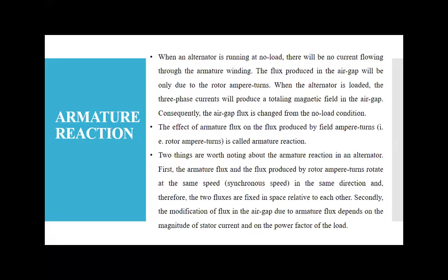Okay, you have a generator. It generates 400 volts or some amount of current. Generally, the capacity of a generator is in the range of MVA, KVA. It is not like a motor, with kilowatt, megawatt like that. Okay, and you already learned why the transformer rating is not in watt and is in VA. The same is applicable for the alternator and generator also.